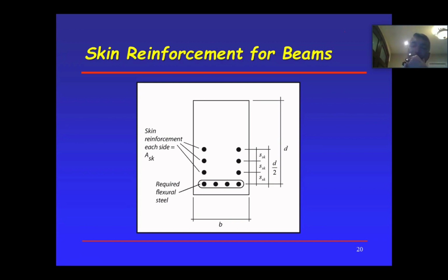What happened on the second floor? Your beams are still on 9 feet on centers. So those columns are going to sit on that beam, therefore that beam is going to be very hefty. Look, when you drive into a parking garage, you'll see it. But you're not going to see a beam there because the architects hide that. They make it look like a piece of precast concrete hanging on the side, but it's really a reinforced beam that you don't see. Okay, so in those cases, your beams will be 36 inches deep. Okay, that's a deep beam. But in buildings, you're not going to hit that.